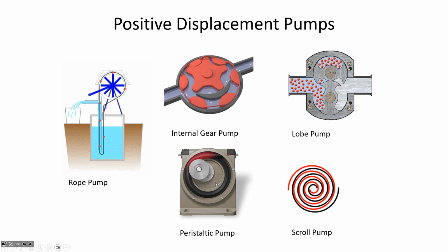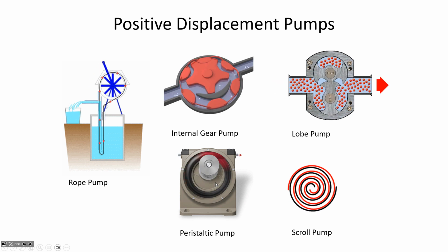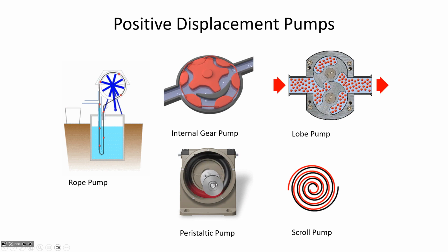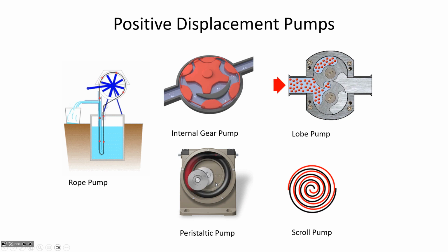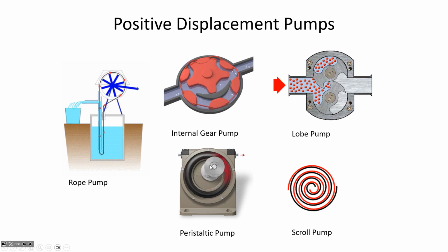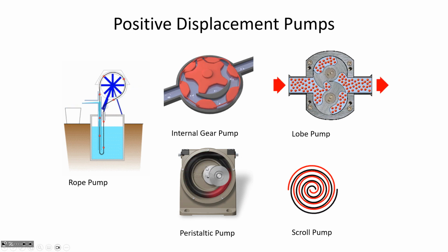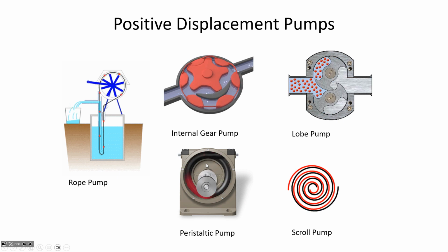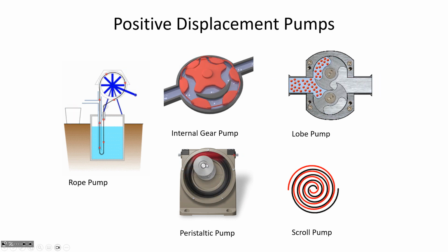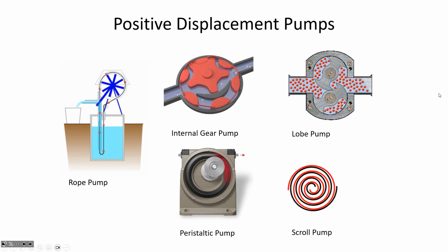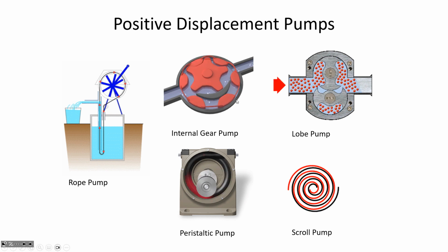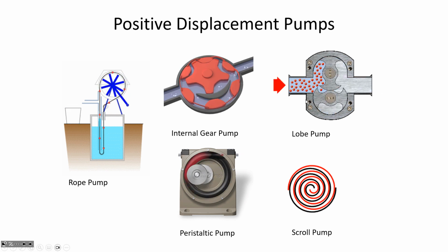A peristaltic pump is beneficial because you can have really direct control over the flow rate, and it's good for really slow flow rates. If you wanted to deliver 1 milliliter per minute, a peristaltic pump could be dialed back really slowly. You could have this turning at just a glacial pace, so it would be a way of delivering a very minute quantity of water, maybe with some chemical dissolved in it, to have a chemical reaction. So these are pretty rare, obscure pump types that you won't often see except in very specific applications where you want direct control over how much flow there is.